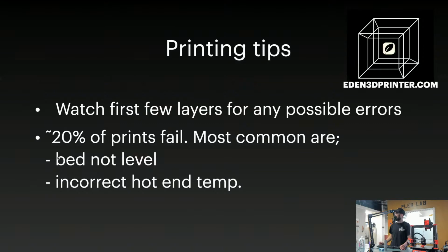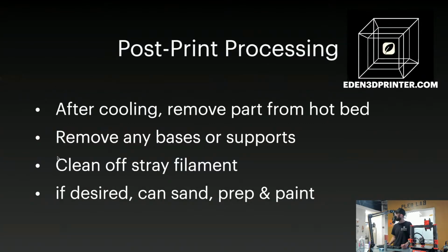And sometimes you might be printing PLA too hot or too cold. Too cold, it will not adhere properly. Too hot, it just smears a little bit and gets a little stringy. So you'll notice that right away. This goes into that fifth and last point: what post-processing is needed.